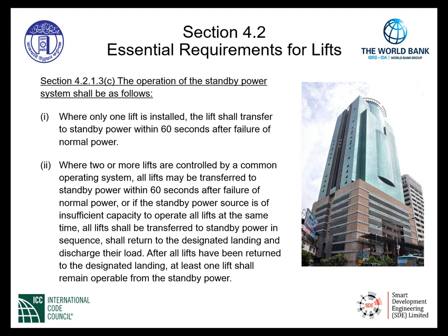Or, if the standby power source is of insufficient capacity to operate all lifts at the same time, all lifts shall be transferred to standby power in sequence, thus lessening the initial load on the system. After all lifts have been returned to the designated landing, at least one lift shall remain operable from the standby power. This section gives us very specific limitations for buildings with one lift or buildings with multiple lifts and the associated time limitation that the standby power must be supplied to the system on a normal power failure.